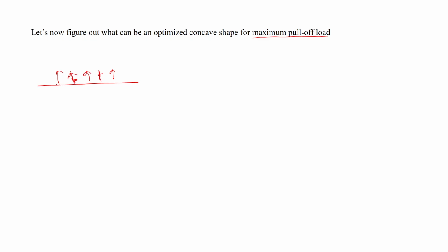So, when you try to pull off this punch, it so happens that whatever is the shape of this head, because of this pull-off load, the stress becomes uniform. In that case there is no stress concentration. That means this P0, P over here, small p, is constant. Or in other words, all parts of this contact area share the load equally.